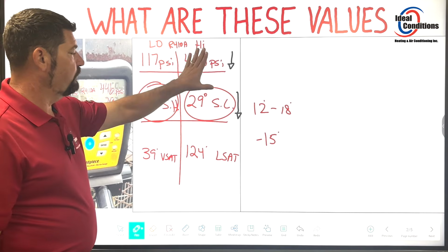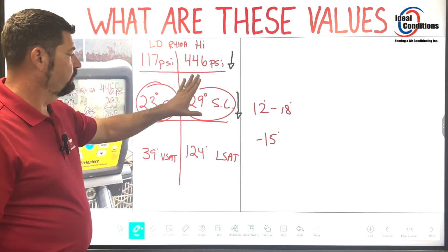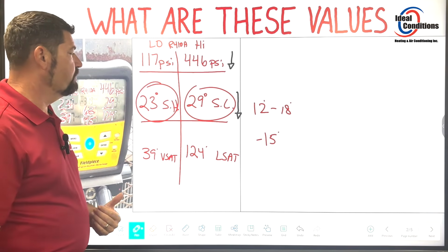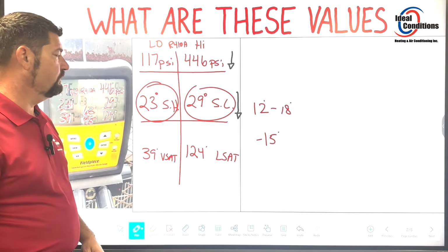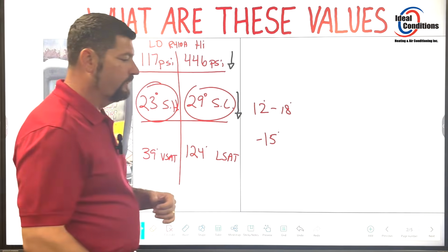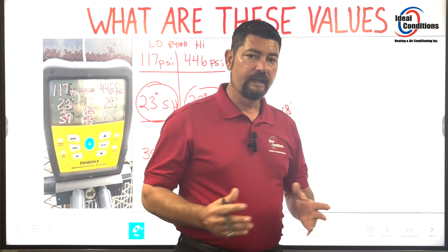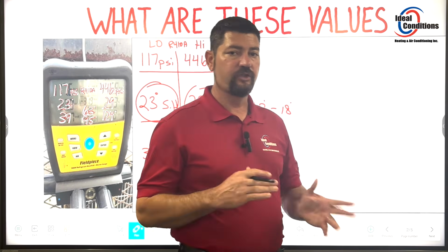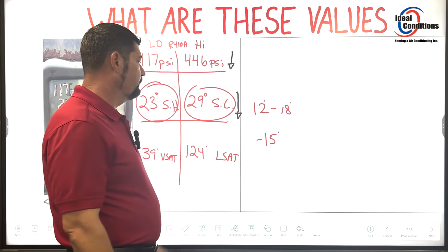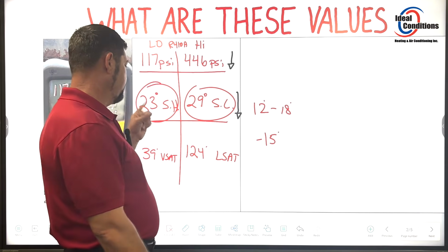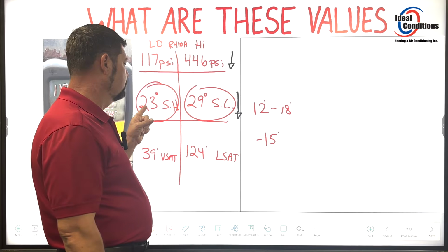Okay, if I was to remove some refrigerant, that's going to leave me better. Now I may not be able to get the subcool all the way down to where I need to. Maybe the expansion valve is just acting funny and it's not going to allow it to adjust to the proper superheat ranges. Maybe I won't be able to get my subcool lower than 10, and maybe that never changes at all.